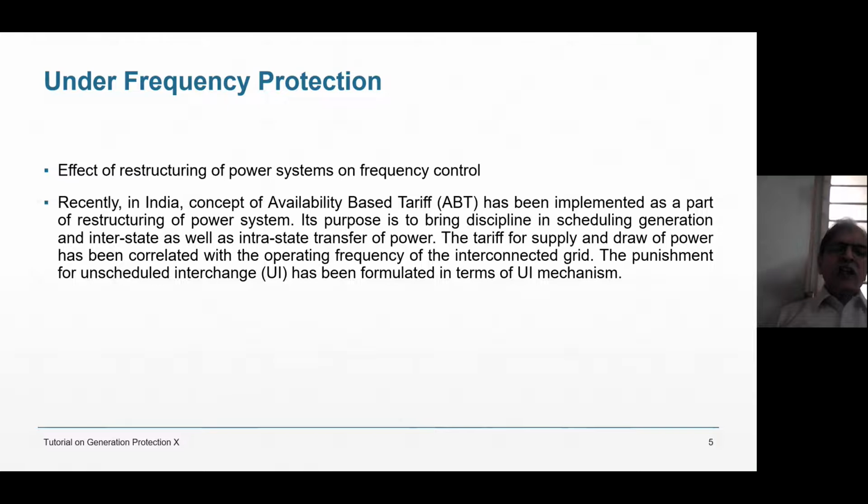Or another thing also, that I have to maintain my power factor. If I'm a consumer, then in BVM Engineering College, I was in charge of the power monitoring committee. So I had to see the power factor continuously. I told some person to check the power factor every half hour, every 15 minutes. Actually, we had an automatic capacitor bank, so that if the power factor is less, the capacitors will be connected. But that was not happening. But manually also we were checking that we have to maintain the power factor at 0.95.